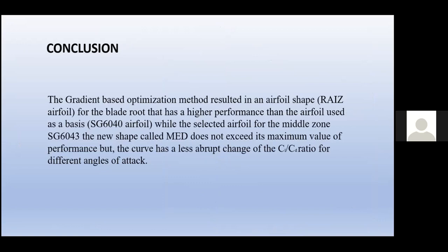In conclusion, it should be noted that with the optimization method used, the airfoil called RISE, compared to its base airfoil SG6040, obtains a higher aerodynamic performance of the lift coefficient over the drag coefficient ratio for different angles of attack, and that the airfoil in the middle zone, although it does not exceed the values reached by SG6043, has a behavior that can be considered favorable.